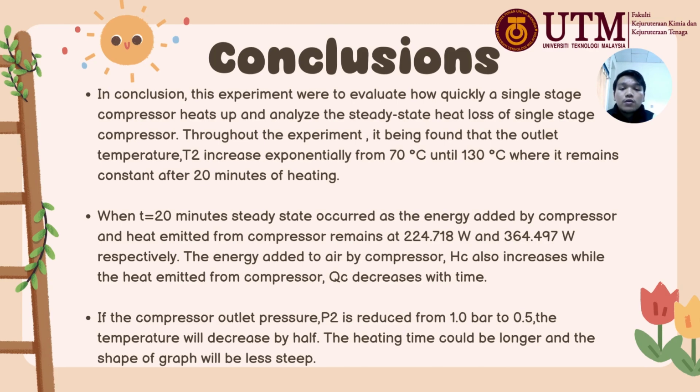Now, I will make a conclusion about this experiment. In this experiment, we aimed to evaluate how quickly a single-stage compressor heats up and analyze the steady-state heat loss of a single-stage compressor. Throughout the experiment, it was found that the outlet temperature, which is T2, increased exponentially from 70 degrees Celsius to 130 degrees Celsius, where it remains constant after 20 minutes of heating.